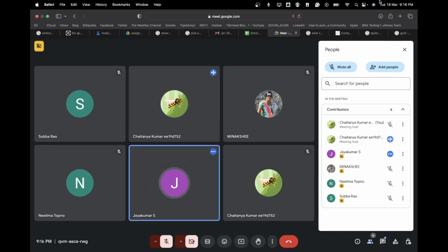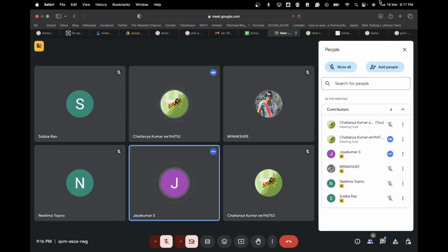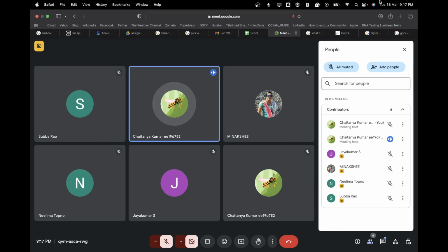Yes, sir. So what we do is we will go procedurally over here. First of all, you have to replace s by j omega. You understand this, right? So we have 1 plus j omega by p. Now what is the phase response? Tan inverse of imaginary part by real part.